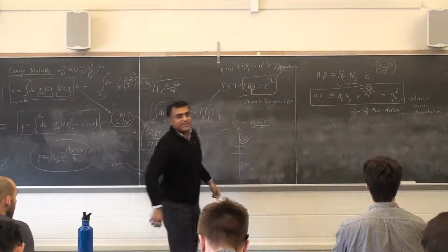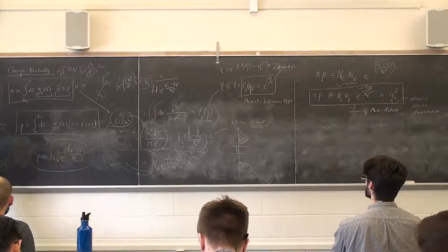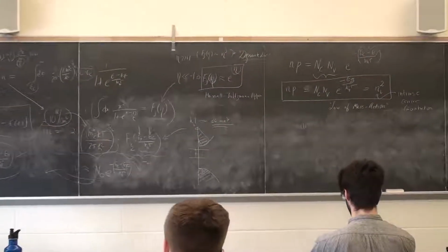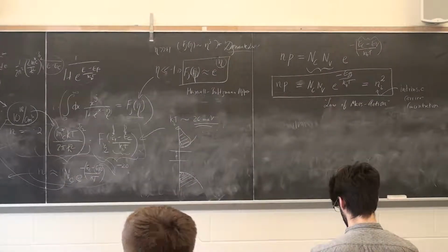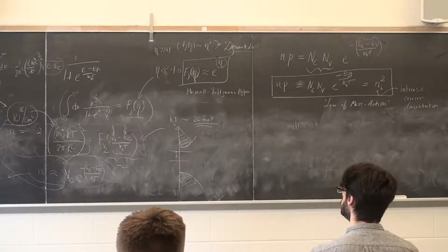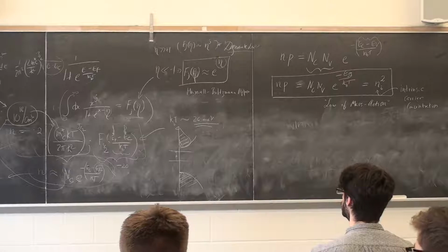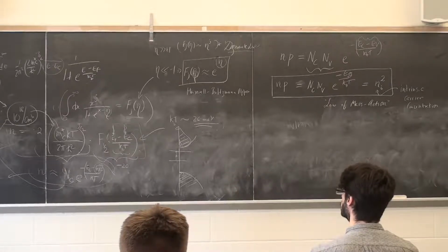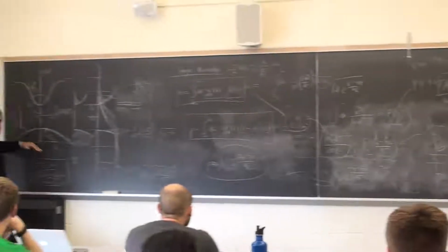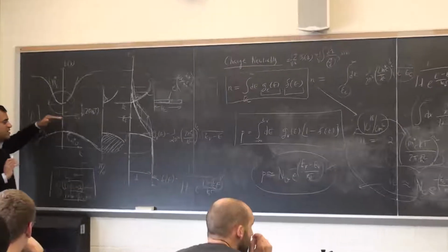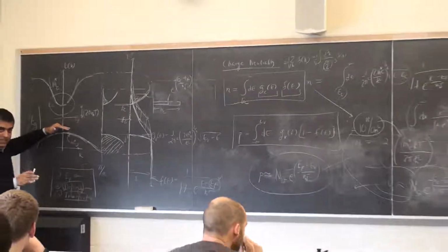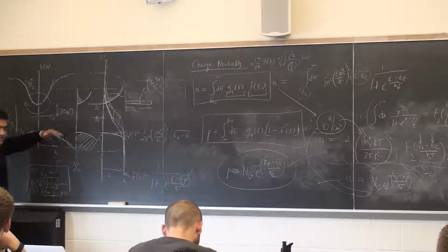Sorry, why is it that when you apply voltage, you're shifting the Fermi level? Yeah. We'll come to that at some point. I don't have to apply voltage. I think I'm kind of jumping ahead a little bit there. Voltage is electrostatics. Essentially, what we are doing is we are moving in carriers from outside, or moving out carriers. Doping is something we're going to talk about today, and we'll see why it will move.